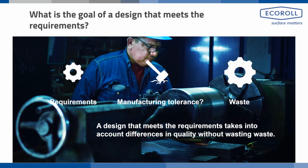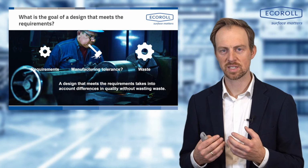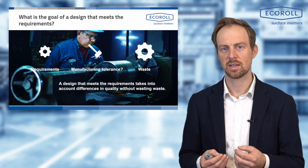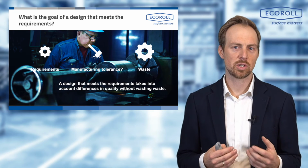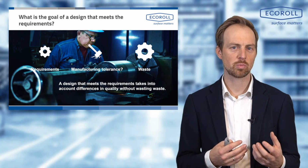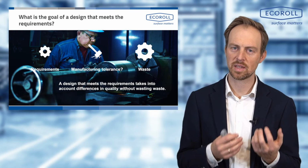It actually becomes a little more complicated, it becomes a little more difficult when we want to exert influence on that, when we incorporate the topic of manufacturing tolerances, manufacturing qualities. We consistently encounter disparities in production. A component will never look exactly the same and possess the exact properties as we have meticulously planned in the computer-aided design CAD software. This implies that we need to consider the manufacturing tolerances in the processes. We need to design the component more robustly because we are aware that the notch effect may be slightly larger than it is supposed to be.